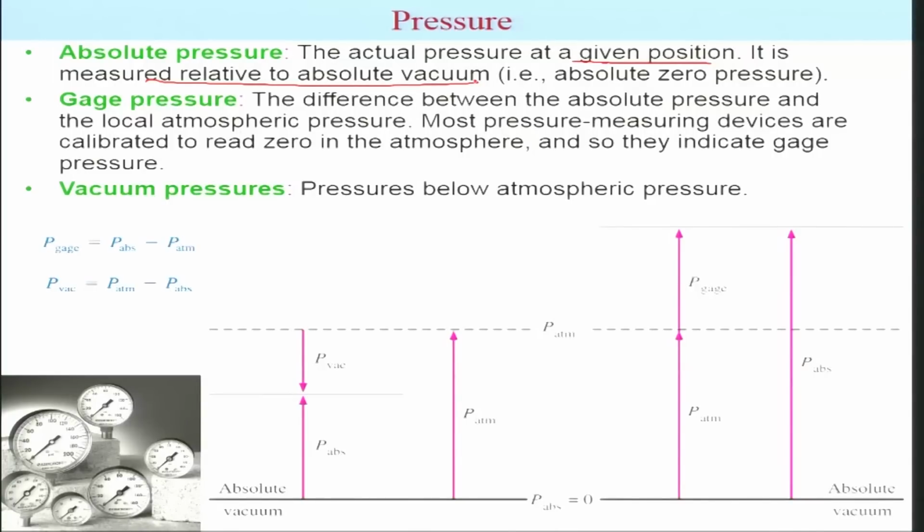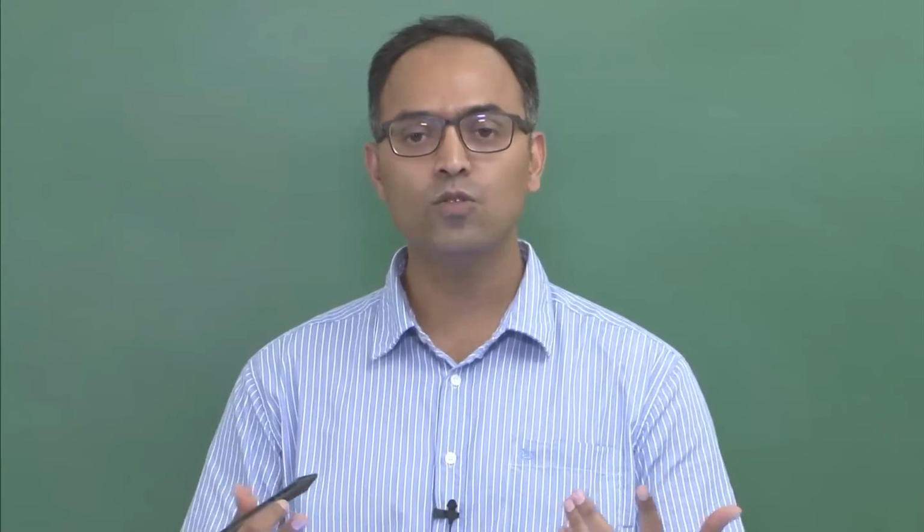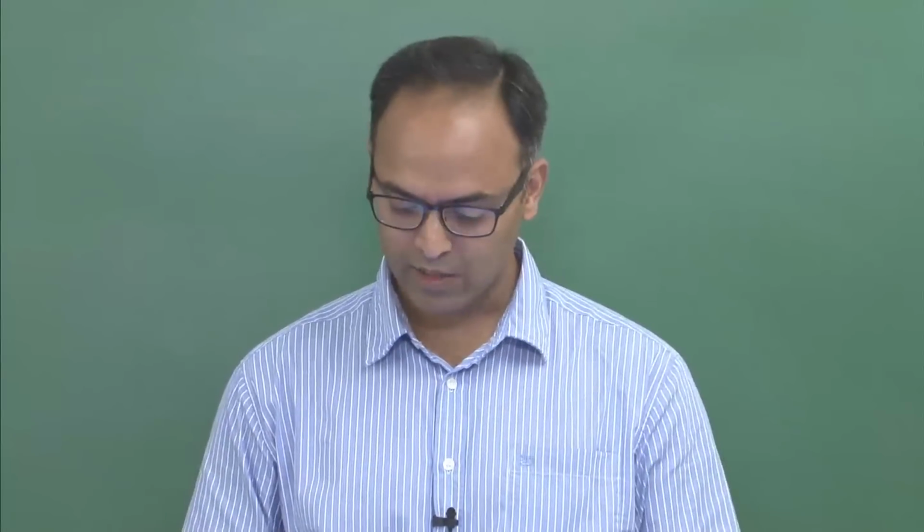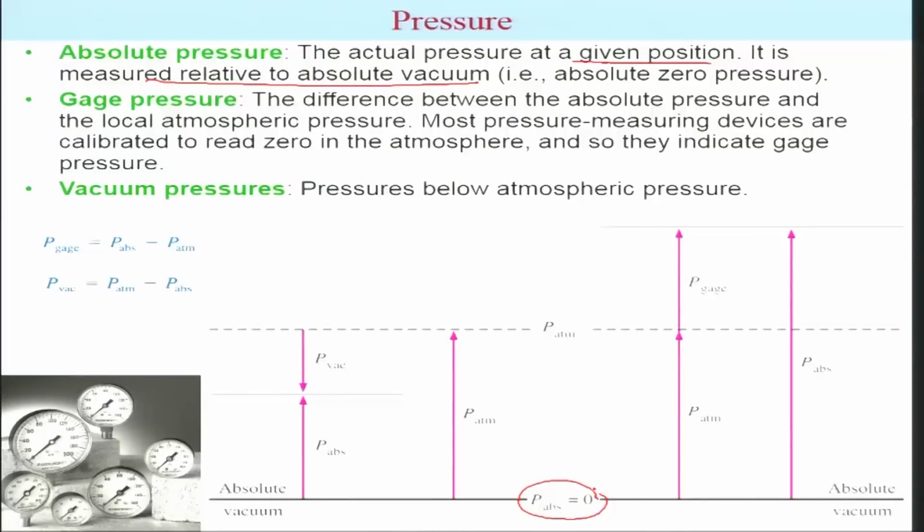It means that you have no gas, nothing in a container, and that gives you a vacuum, and there are no molecules imparting any pressure on the container, and we can refer to that as vacuum pressure, which is 0. So you have this absolute pressure, where vacuum pressure is 0, and then you have the pressure which you desire. Again this is absolute, and this is the value here, and this is, let's say, the atmospheric pressure. So the difference with respect to atmospheric pressure is called gauge pressure. So this is the one.